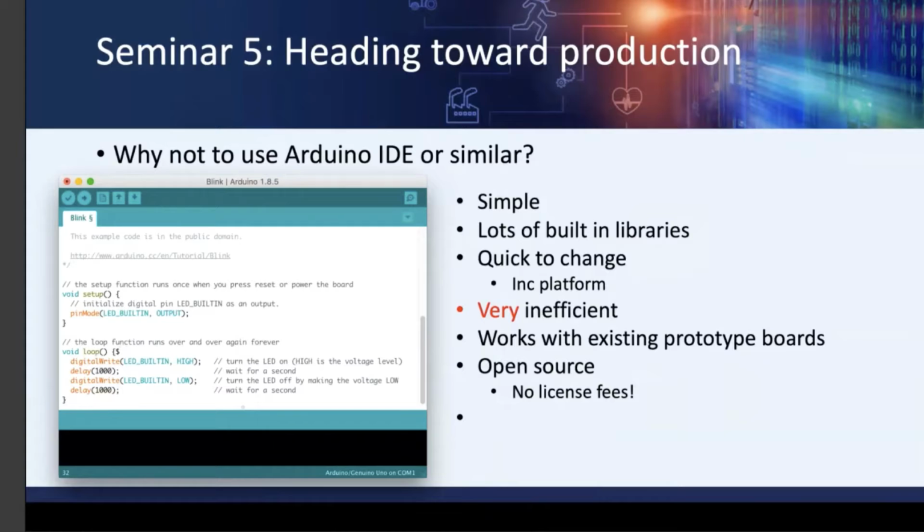The problem with this sort of programming is you're constantly consuming power to wait for something. So one of the best ways to overcome that is to put your system in a sleep mode. You turn off some of the peripherals of your microcontroller that you don't need. So that's going to be sleep mode. And then when an event comes in, that change in temperature or change in pressure, that can be an interrupt. With something like that, you have to stop the current flow of your program, go handle that interrupt, and come back.